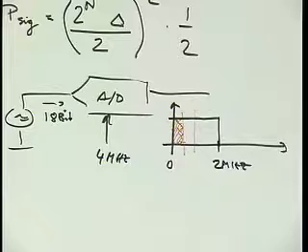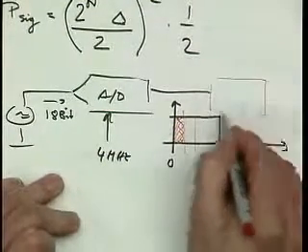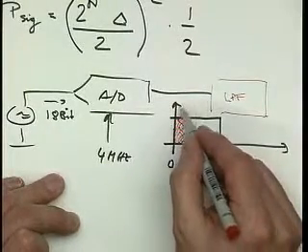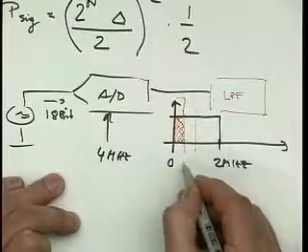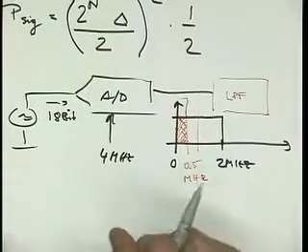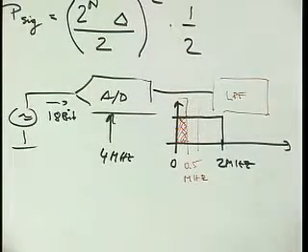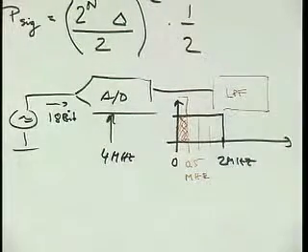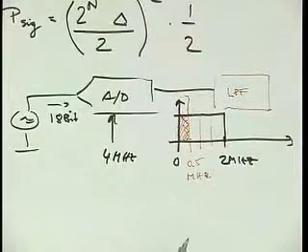Okay. How do you do that? Well, it's very simple. We put here a low-pass filter. And that low-pass filter filters everything out that is above 0.5 megahertz. It filters away all the noise, so it filters these 3 slices of noise away. Now the noise is down. But of course, it also does away with any signal that was up at these higher frequencies. So we kind of trade bandwidth for noise. So there is no miracle, right?